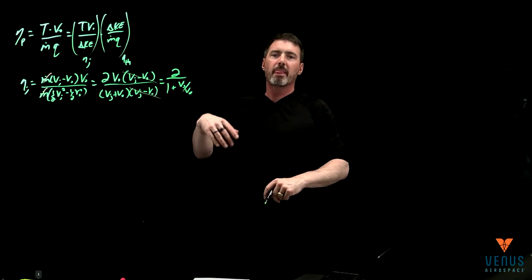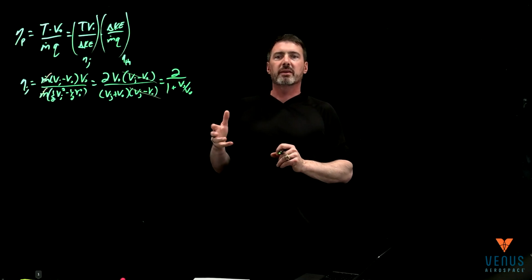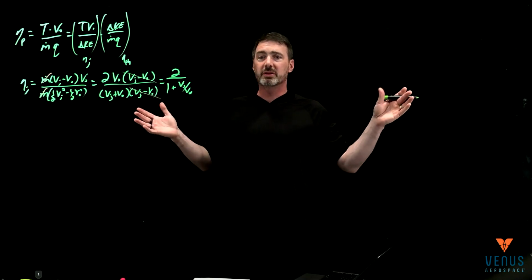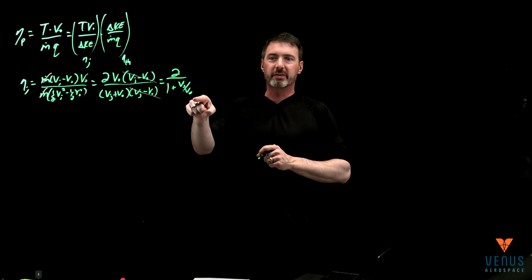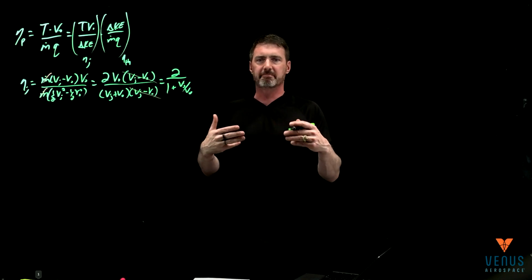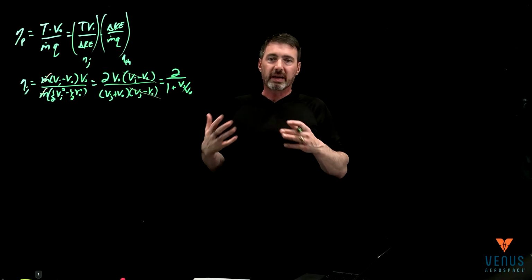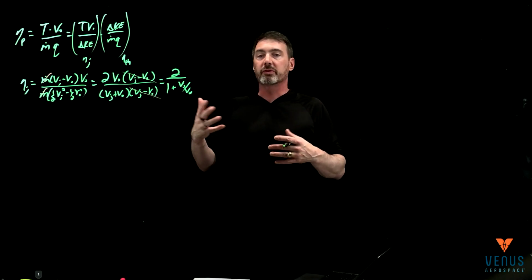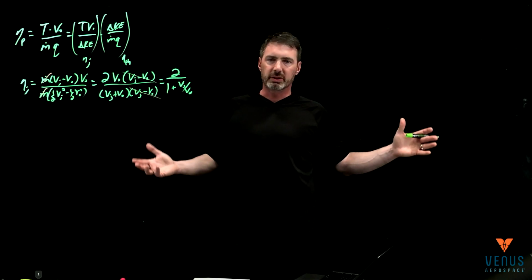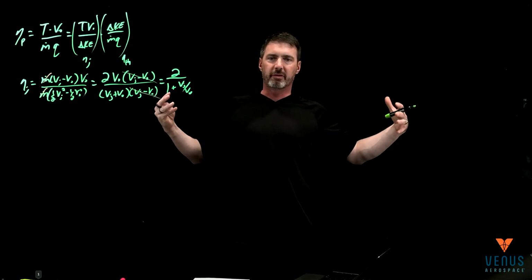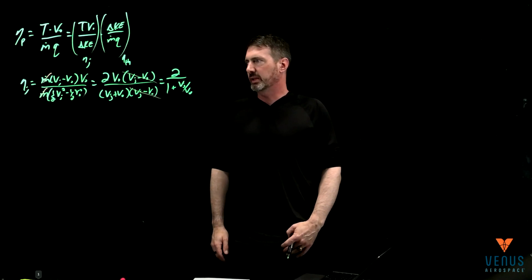It always feels a little funny, but what this means is that higher jet efficiency comes from taking a whole bunch of air and only making it slightly different than v0. In the limit where vjet equals v0, your efficiency is 100%, but you actually made no thrust, because your thrust term went to 0. So you always have to have some jet velocity bigger than v0, but the closer it is to v0, the better. That has nothing to do with hypersonic flight. Even a big jet engine has a big fan grabbing a lot of air and barely making it faster. That's actually high jet efficiency.